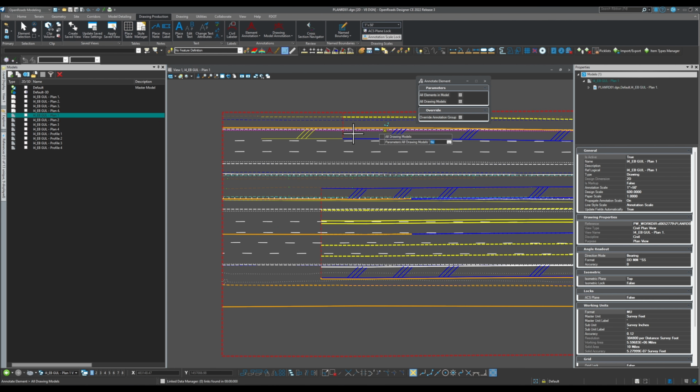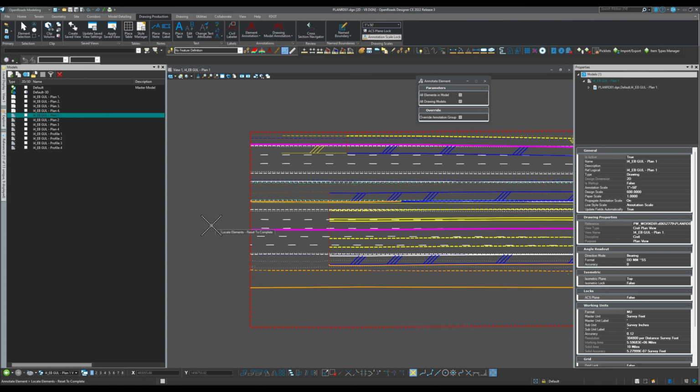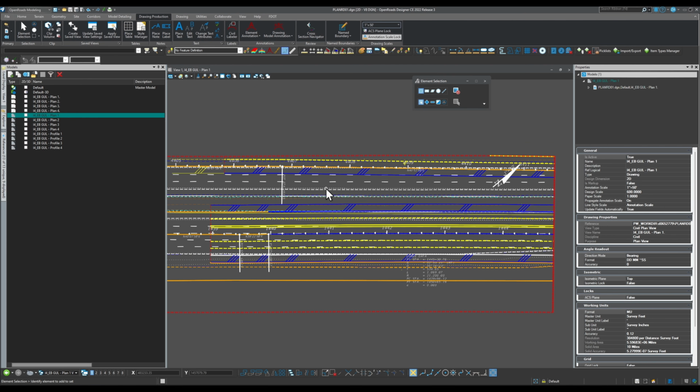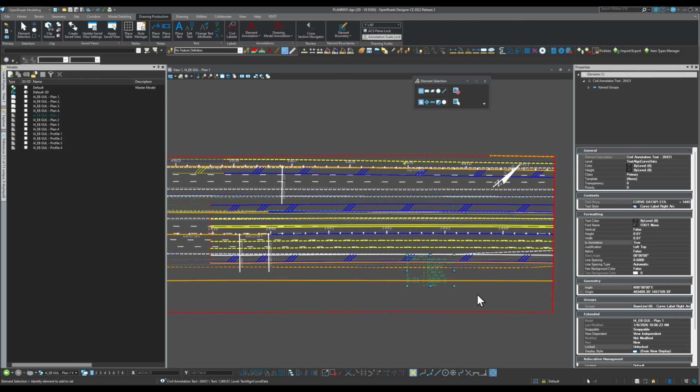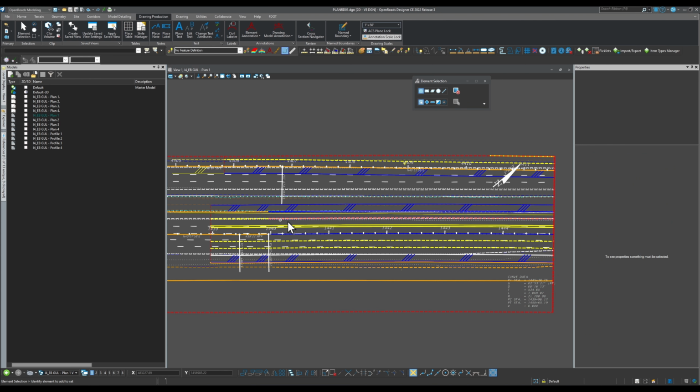For example, I have a bunch of alignments here, but I want to annotate only one, right? So again, you can have your annotation in a text file. We already talked about that, but if I want to just annotate this one, just this view, I can click on the element itself. I want to annotate this one, for example, and I just want to annotate this one. That's it. So I selected them, ta-da, and that's the only thing it annotated for me. For whatever I'm trying to achieve for whatever I have here, right? Again, it depends on whatever task you have.